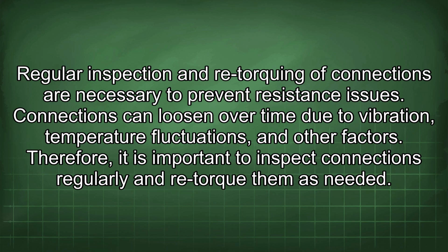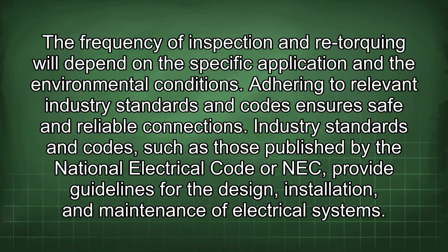Connections can loosen over time due to vibration, temperature fluctuations, and other factors. Therefore, it is important to inspect connections regularly and retorque them as needed. The frequency of inspection and retorquing will depend on the specific application and the environmental conditions.